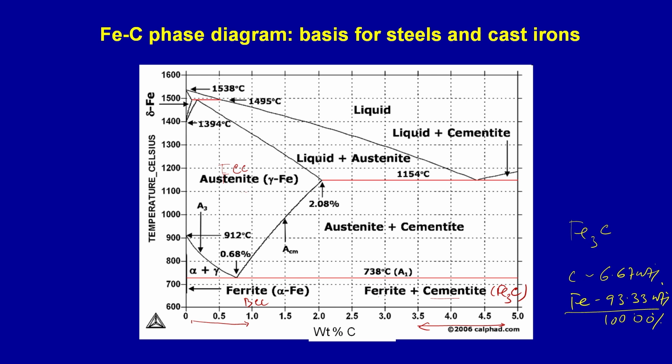That corresponds to iron carbide, Fe3C, which is a major phase in steels and cast irons. Mostly in steels, Fe3C is present as an important phase in the microstructure. But as you add carbon, carbon can also get into the iron lattice or crystal structure. This is very important, and this is something we learned in the last lecture also, and we will learn more here.